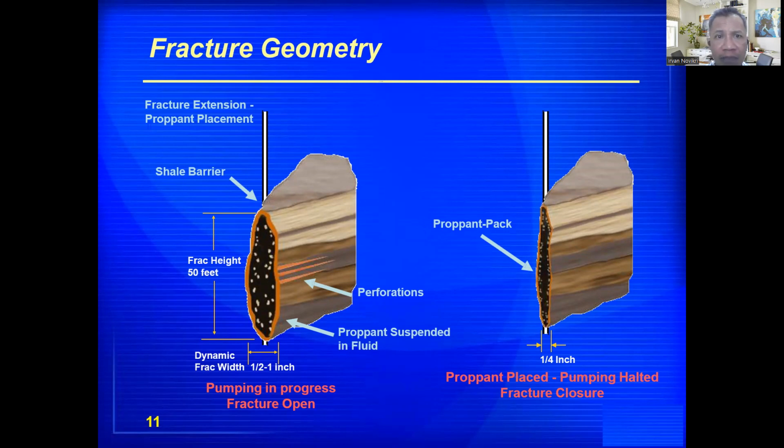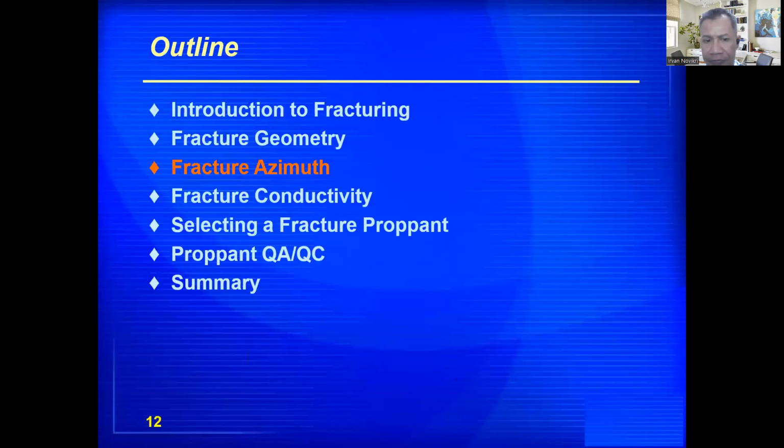And then once we have stopped pumping the fracture, Mother Nature is pushing on it with stress, and it will actually try to close. It is the proppant that we put in there that keeps that fracture from closing. Without the proppant, the fracture will not only close, but it will seal back up.